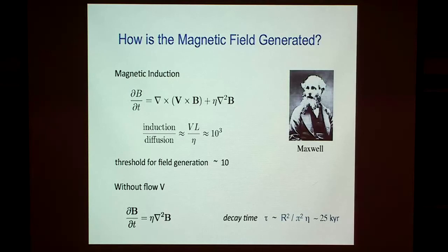Well, if you were to plot the spectrum, for example, of those flows that I showed, where the scale is getting very small, what you would expect to see is kind of a white spectrum, and then it basically tails off where viscosity plays a role. So it's not like when you see those small scales that all the flow is concentrated in a small peak with a relatively narrow range of length scales. It's very broad scale, right? Your eye picks up the contrasts where they're very sharp, but what your eye is picking up is essentially something close to the cusp of that spectrum. But the point is that you've got power in long scales.